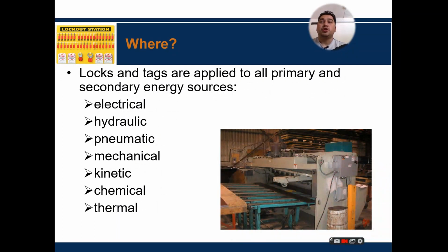Now, where you should apply this lockout and tagout. Locks and tags are applied to all primary and secondary energy sources like electrical, hydraulic, pneumatic, mechanical, kinetic, chemical, and thermal. Wherever these are included, you have to use your lockout tagout procedure.